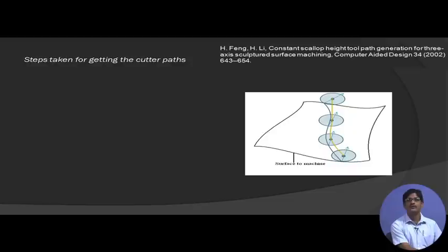We remove all the construction lines. Next, we find out the intersections of the swept sections of the cutter with a surface offset from the design surface by the scallop height. So, this surface is away from the design surface, normal to it at all those respective positions by the scallop height, and this way we are determining the tips of the scallop curve at these locations on the swept sections